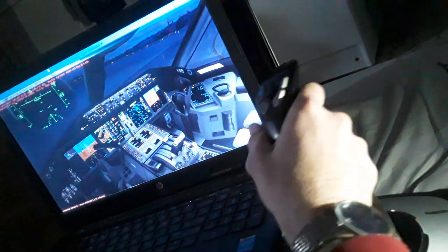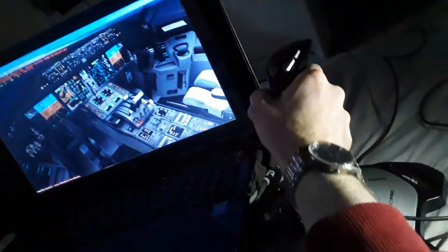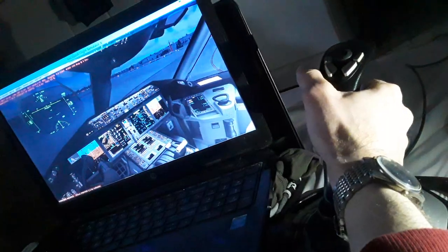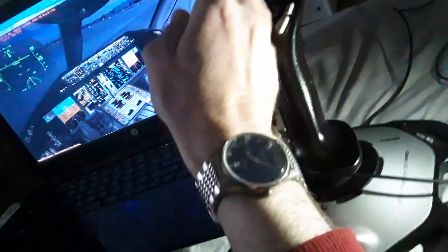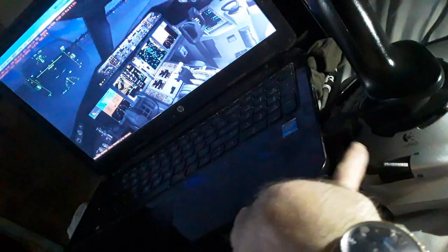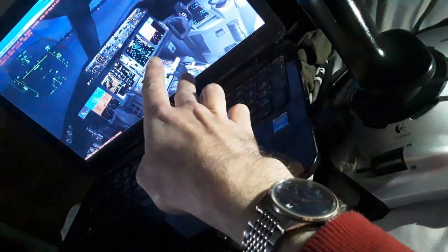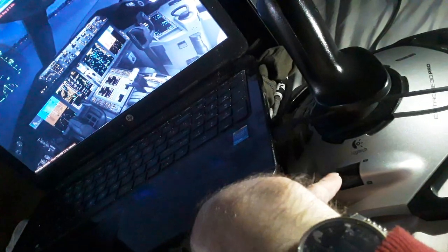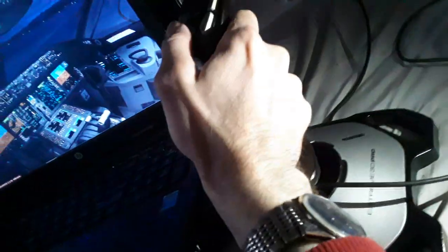So you make right and left turns, and you climb and you descend like this. Climb, descend, make turns to the right, make turns to the left. Very easy. Also you have the thrust control, thrust levers over here, actuate the thrust. Very easy. You see how many degrees. You move the thrust levers forward, full takeoff, or back to the idle thrust reverse, also horizontal.